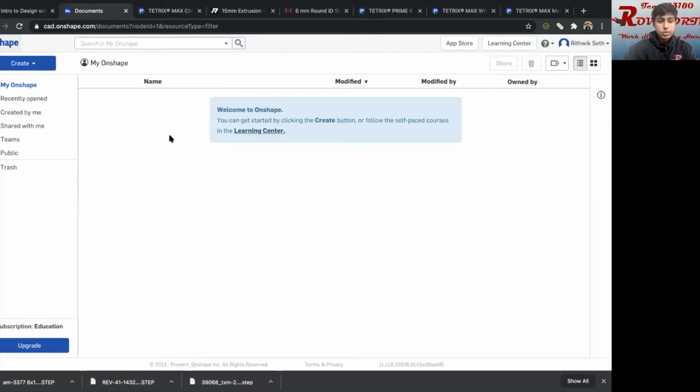All right, after you've downloaded all 6, you're going to click create on your Onshape dashboard and you're not going to click document or folders, you're going to click import files. I'm not sure if you'll be able to see the pop-up that happens when I click import files. If you are, you'll see your computer system finder. After you find that, you'll be greeted with all the parts you've downloaded. So this would mean that you have to upload these parts, and you're just going to click open.